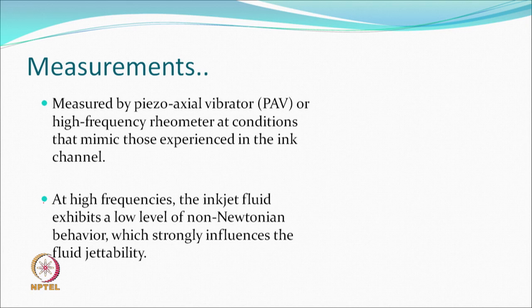And so, the method that we used earlier for viscosity measurements may not be very suitable for this type of material, because the ink is experiencing various types of pulses, pushes by actuators at very high frequencies, and therefore, the behavior should also be tested by instruments which work at high frequency.